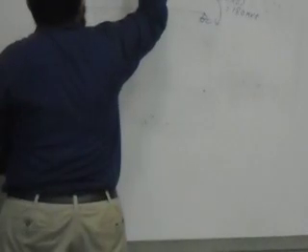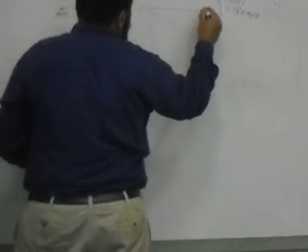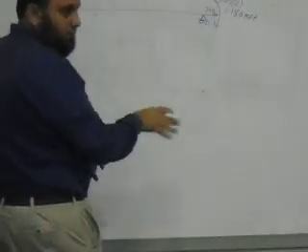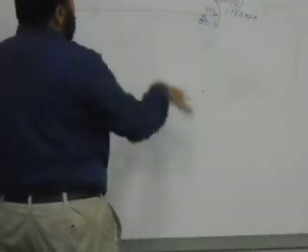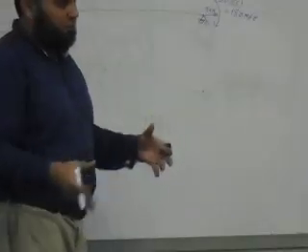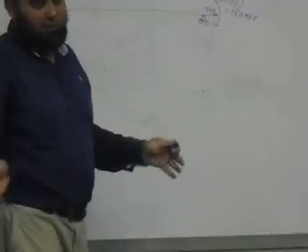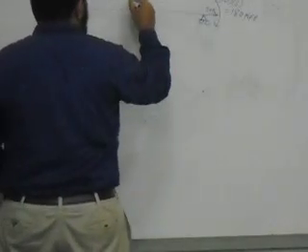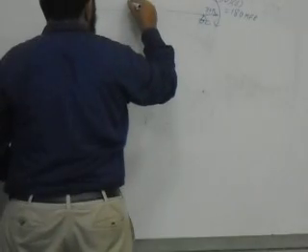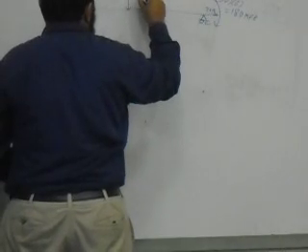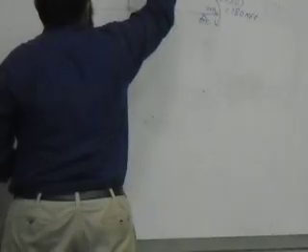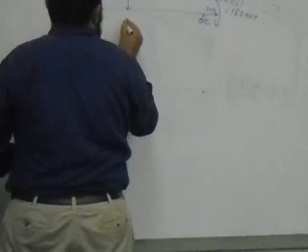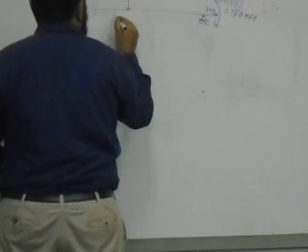Here, in addition to the 30 kip force, the force moved down with me. But this force is axial to my member, it will not affect the demand moment at all, so removing the force doesn't make a difference. Here the 5 kip is going down, it doesn't matter. But what will this force cause at B? 15 times 4. Bravo, so here I'll have another moment like this.